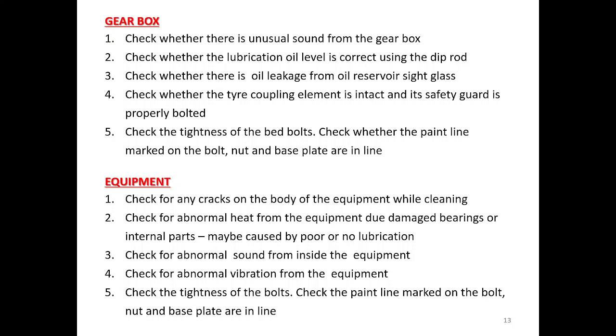Check for abnormal sound from inside the equipment due to loose internal or damaged parts. Check for abnormal vibration from the equipment due to loose nuts and bolts. Check for the tightness of bolts. Check that the black paint marked on the bolt, nut and base plates are in line.